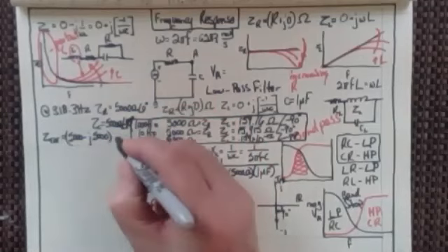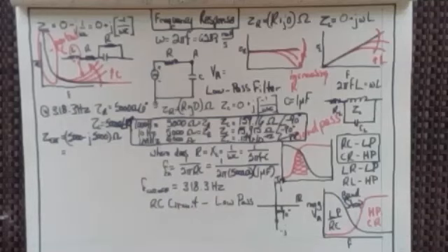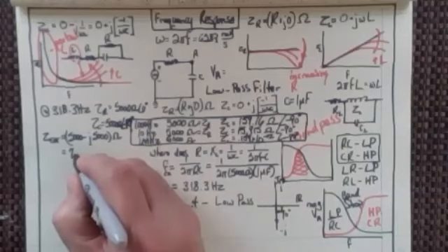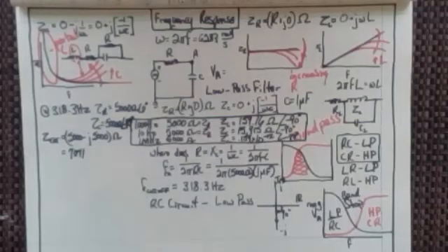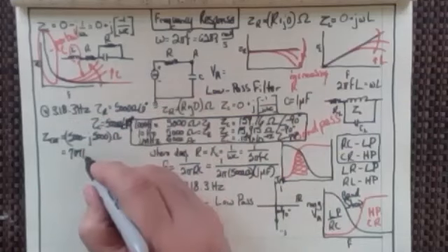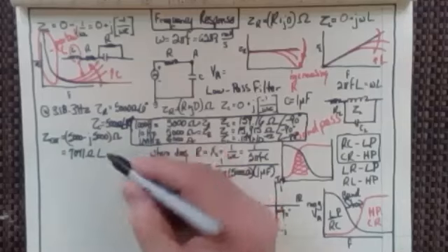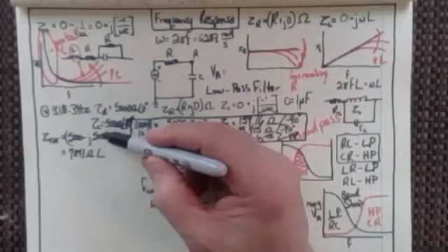Ohms. If I wanted to write that out as a phasor, I could take 5,000 squared plus 5,000 squared, and then take the square root of that, and that, of course, gives me 7,071. Keeps coming back at you all the time, doesn't it? 1 over the square root of 2. 7,071 ohms at an angle of, now let's think about this. We've got minus 45 degrees, right?